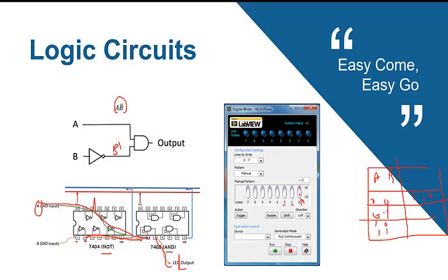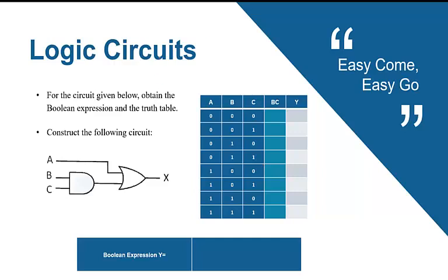After that, I will test the second case scenario. A is 0, so I will make this 0, while B is 1, so I will switch the second switch to be on and check the output of the LED. After that, I will make A as 1 and B as 0, and check. Last one, I will make both A and B on, and check the LED output. And of course you have to run in order to check the influence of the logic circuit on the LED as output. So you are going to make this example in your lab.